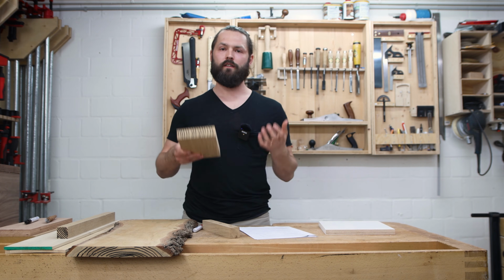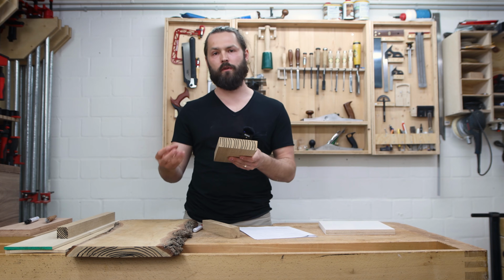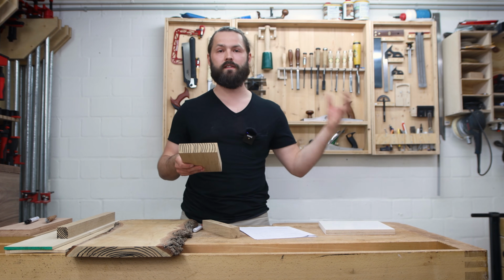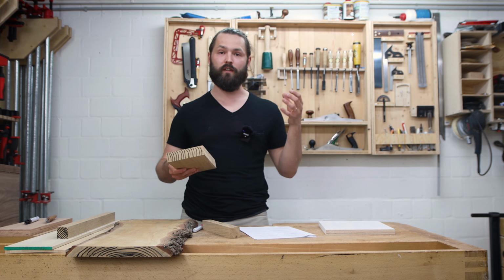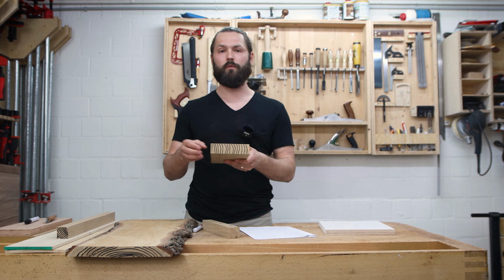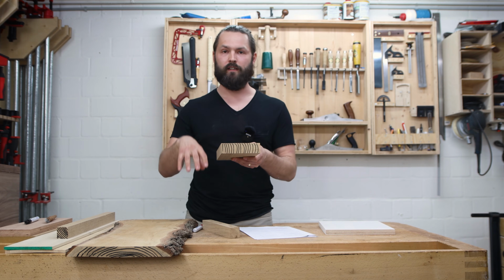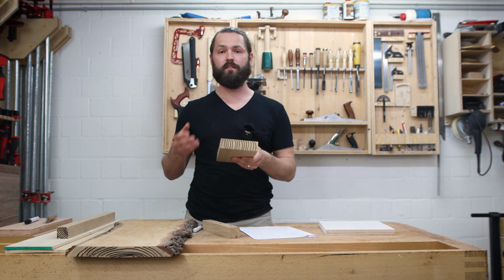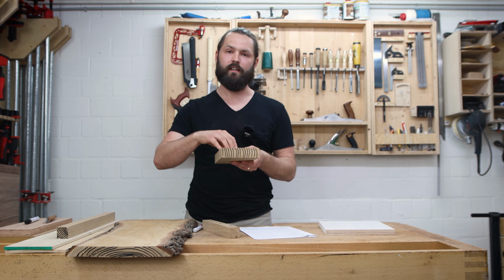So if you build your furniture piece in the garage outside, there's a higher moisture content, maybe around 15% or so, and you want to ship it somewhere, for example to the southwest of the US, where it's only 4%, your wood will move significantly more than in this case where I have my lumber here in my house already for building it.